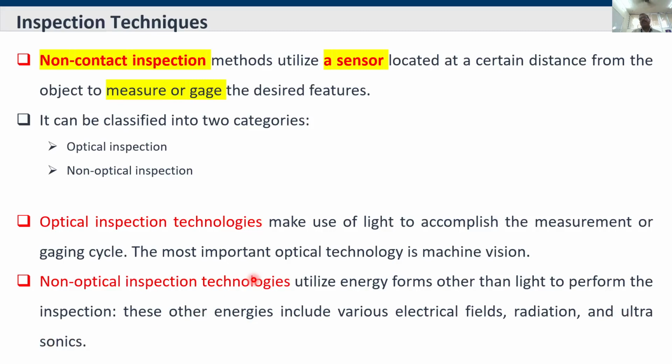Okay, so for example, in the casting process, you might remember you studied casting in your manufacturing technology. In casting you will have a cavity. The cavity is made from the casting process, like you prepare a mold, put in a pattern and remove the pattern. After that you have the cavity, right? If you pour molten metal into the cavity and give solidification time, once solidified you can take the casted part out. Then you want to see whether any defects are available, not outside, but internally.